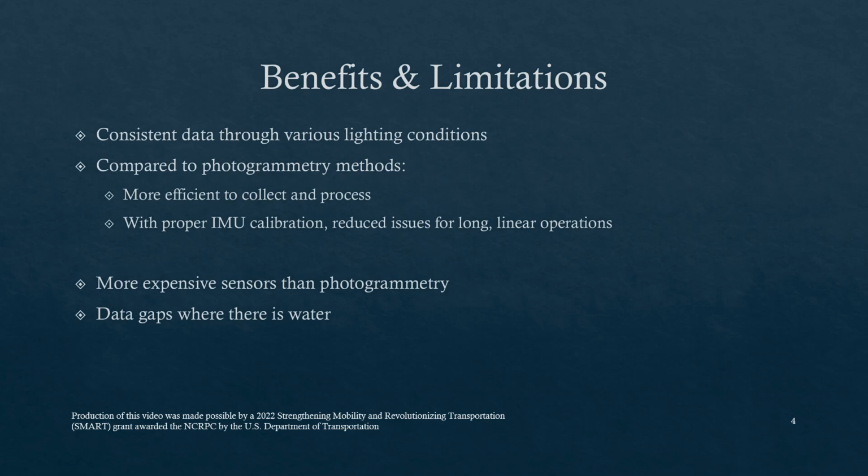You'll see later that the amount of overlap with LiDAR is significantly reduced as compared to photogrammetry. And with a proper IMU calibration, which is absolutely critical to good LiDAR data, you have fewer issues for long linear operations. Specific to road inspection or mapping, where you have a long linear stretch, that can pose some unique difficulties with photogrammetry, whereas with LiDAR, since it's a scanning technology, it actually works fairly well.